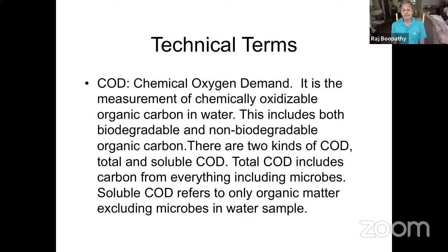And then the soluble COD refers to when you filter the sample. So what is dissolved in the water is what you're measuring. So we have total COD and soluble COD, which excludes biomass in the water sample.